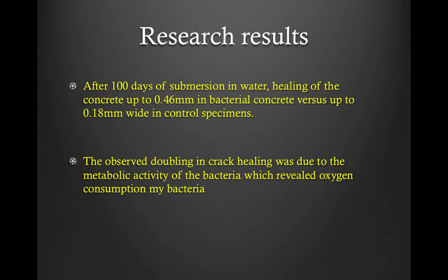The results of the experiment: after 100 days of immersion in water, experimental results revealed healing of cracks up to 0.46 millimeters wide in bacterial concrete versus up to 0.18 millimeters wide in control specimens. The observed doubling in crack healing was due to the metabolic activity of the bacteria consuming oxygen.